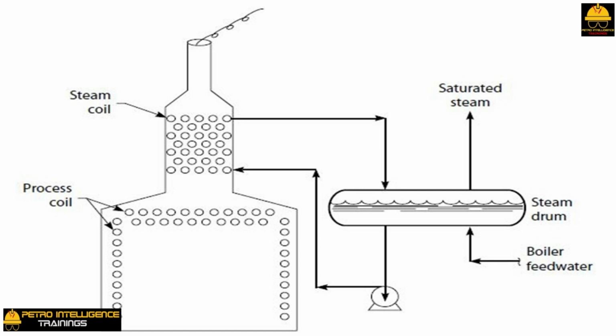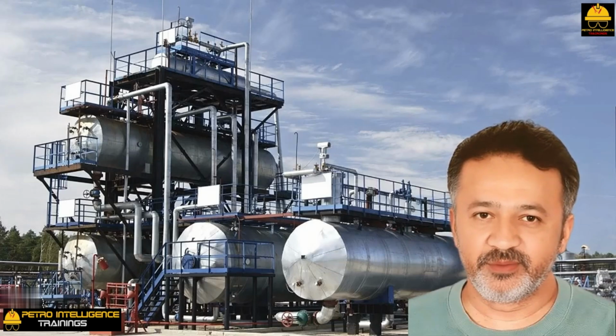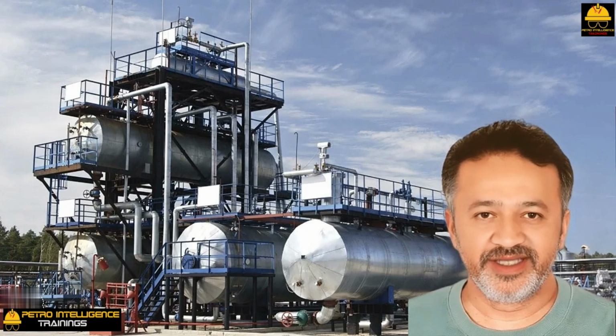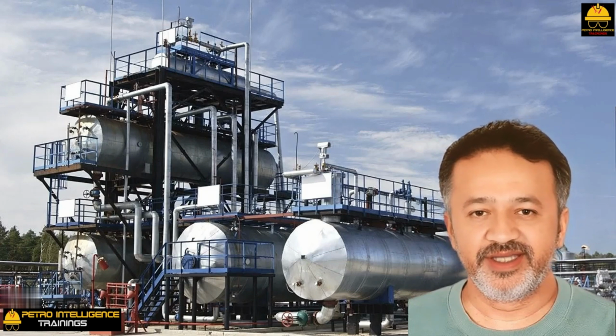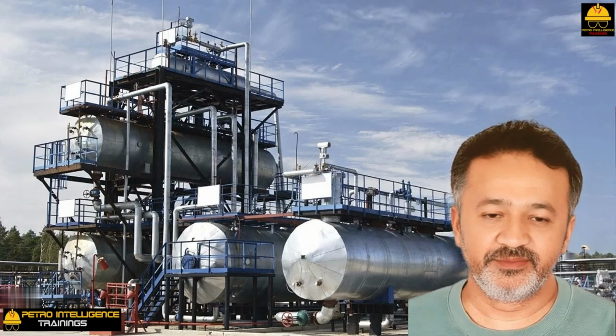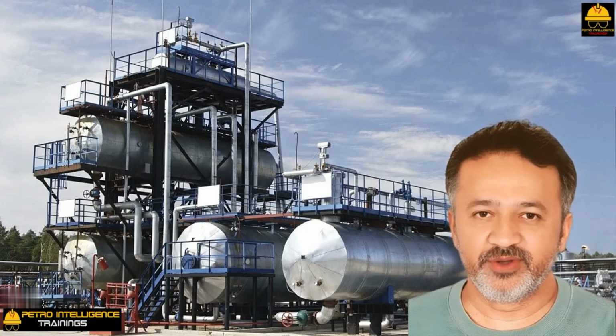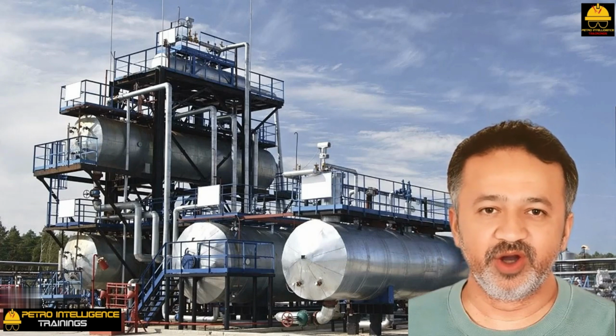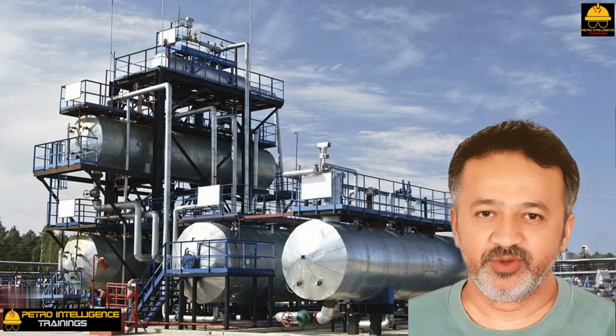It is good design and operating practice to keep the percent of water vaporized in the steam generating coils to well less than 50%. Higher rates of vaporization promote the laydown of salts inside the convective tubes. Low water circulation rates will lead to tube leaks. It is probably best to consume steam generated in small waste heat boilers locally in steam reboilers and preheaters. Turbine drivers are best powered by boiler house steam, where steam quality is more closely monitored and controlled.